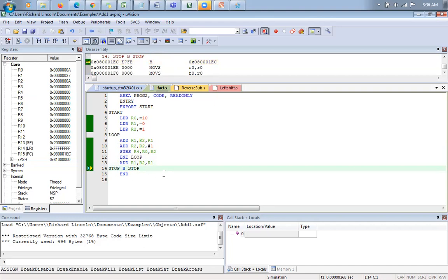If you place the mouse cursor on your registers, you should be able to see R0 value A, just as we had given, and R1 final value we have 37. Initially we had loaded 0, and right now it's 37, and R2 has attained its maximum value. And R4 is 0 because it has become 10. R0 is 10 and R2 is also 10. So 10 minus 10 is 0. R4 is 0 here.